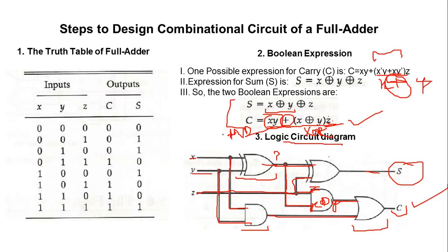You can again look thoroughly at this circuit diagram, at how it has been designed. It is very simple, though if you are doing it for the very first time, you need to understand how we are representing the logic circuits. The idea is that I need not repeat the same thing for carry, like for x XOR y I need not design it again. Reason being, it will ultimately make this particular circuit more complex, and along with that it will also increase the cost of the circuit. So whenever we are designing the circuit, we have to focus on both parts. Cost should also be optimized.